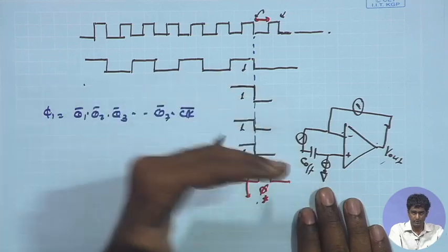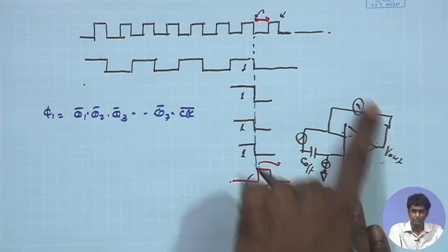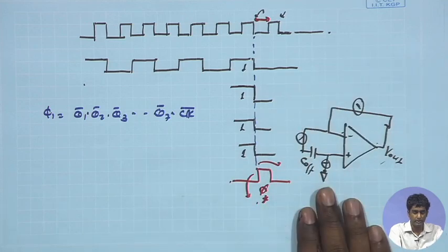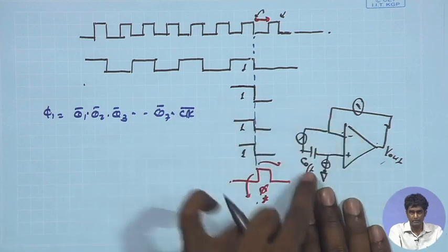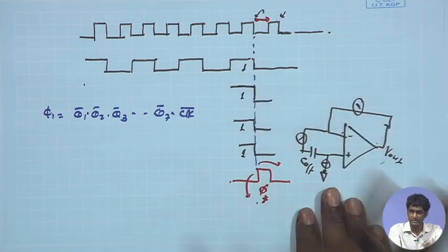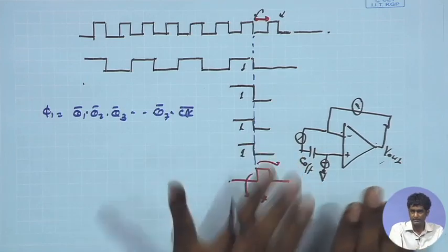That is a relatively less severe constraint, but here the constraint can be more critical, because here you need to make sure that the open loop bandwidth of the amplifier is close to 1 megahertz, despite the large load capacitance and the compensation capacitance coming into picture. So, that was the more serious constraint that we discussed in the last class.